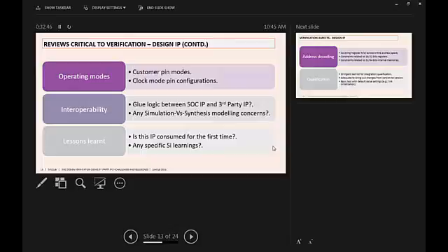When you bring that design IP into your system, it's not always going to work just like that. Even though they say they support the common bus system, you may have to incorporate some glue logic between your SoC bus system and the IP, before you connect it for your own extended functionality. That's why I said in the SoC fabric you will be doing some tweaks.